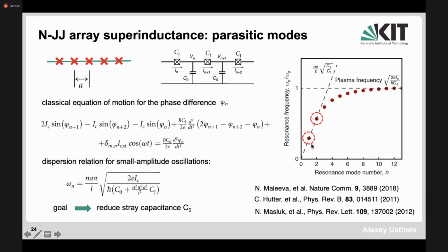And what happens in fluxonium qubits is that these modes sort of conflict with the modes of the fluxon. They mix with modes of the fluxonium device, fluxonium Hamiltonian, because these particular modes are not included in the full spectrum of the Hamiltonian, because in the Hamiltonian this series inductance is approximated simply by a lumped inductance element, and interaction with these modes often makes the operation of the device impossible.